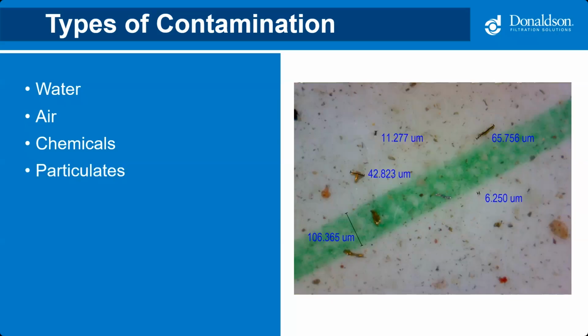And last, but definitely not least, is particulate contamination. This is responsible for much of the visible damage to final drives, hydraulic motors, cylinders. That sand, silt, and dust, and potentially soot, typically reach that hydraulic system through leaky seals or lack of breather filtration. Even though particulates account for the majority of contamination within a hydraulic circuit, it's arguably the segment that we have the most control over.